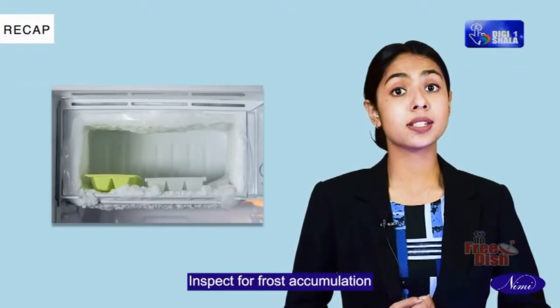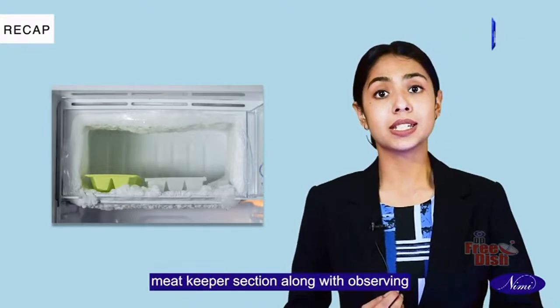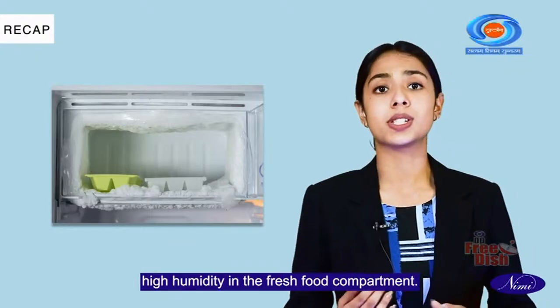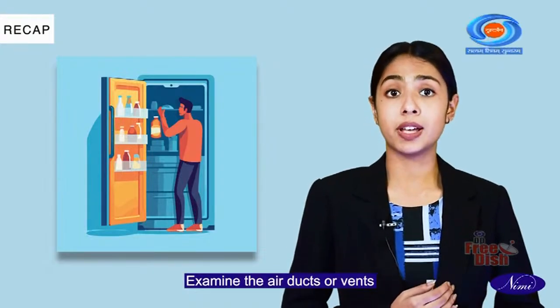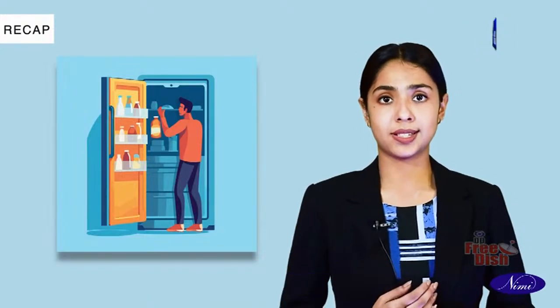Inspect for frost accumulation in the freezer compartments and meat keeper section, along with observing high humidity in the fresh food compartment. Examine the air ducts or vents for any visible blockages or obstructions.